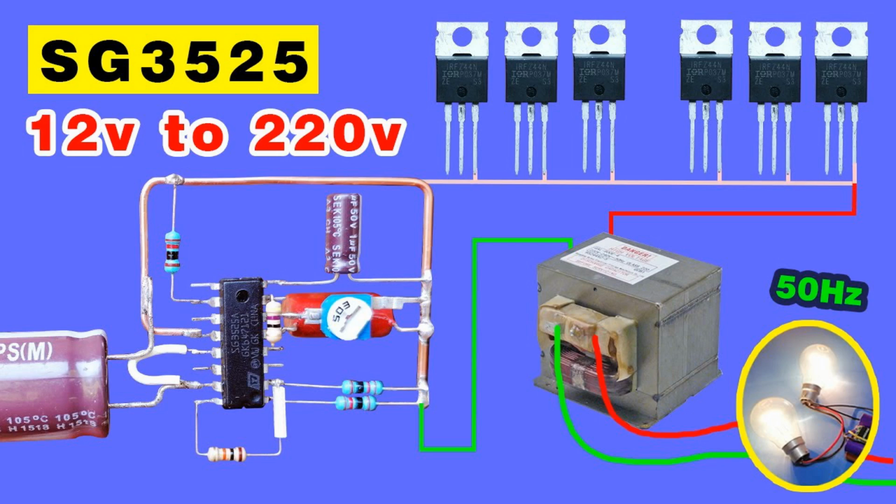Power management mechanism. Switching mode. MOSFETs operate in switching mode for most power management applications. They switch between fully on, low resistance, and fully off, high resistance, states, minimizing the time spent in transitional states where power loss is higher.